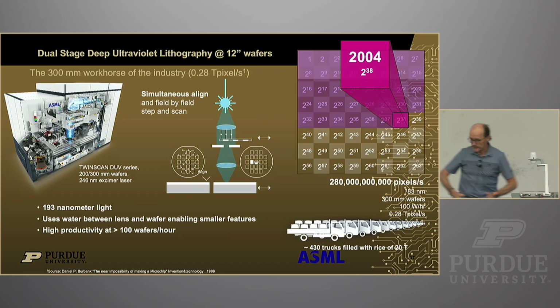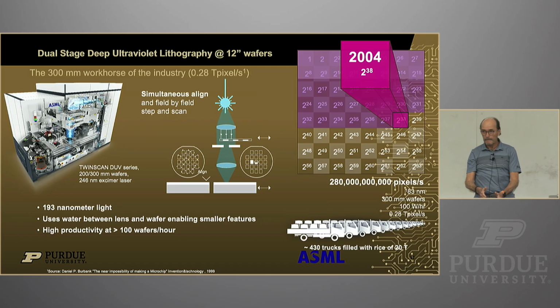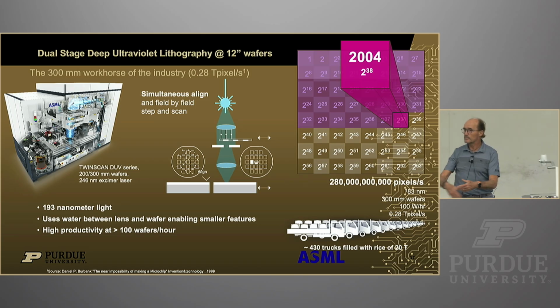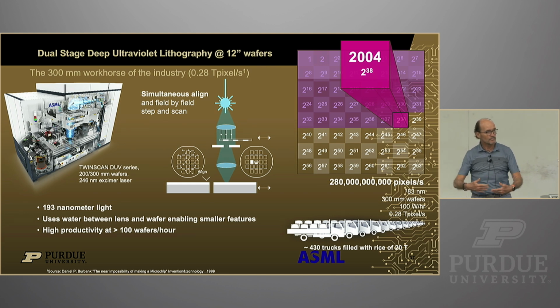I now move it here under the lens where the exposure happens. This wafer table moves back here. The old wafer that is exposed goes off. New wafer comes in. I repeat that, doing the alignment here while I'm doing the exposure here. We drive more and more productivity. No waiting to expose because first you need to do alignment.